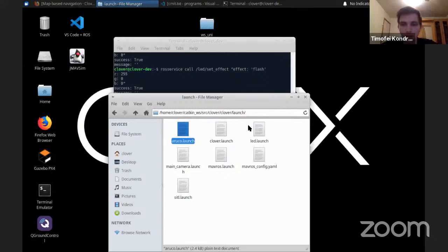So you don't need to use time.sleep. Never use time.sleep neither in real world or in simulator, because time.sleep will use your computer's time to wait, but rospy.sleep will use ROS time, and this is much more precise, and there will be no rush. So if you use time.sleep, it will be just not enough time for the drone to take off, for example.